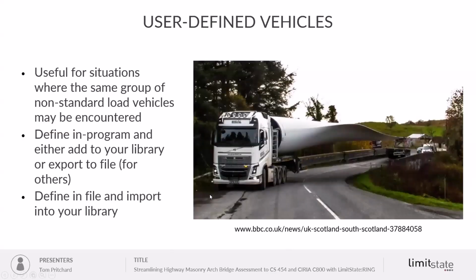The other thing that's quite useful is the ability to put in user-defined vehicles, obviously for situations where your same group of non-standard load vehicles may be encountered. So for instance, if you're taking a wind turbine blade from inshore to the shore or something like that, you can define that in the program and either add it to your own library or export it to file for others to use. And it's a very quick and easy method to be able to do that.